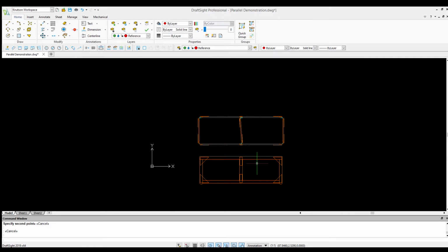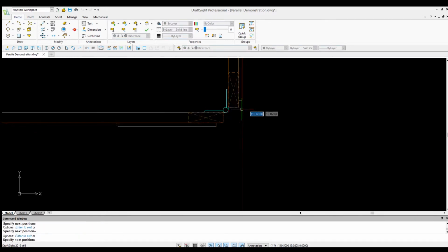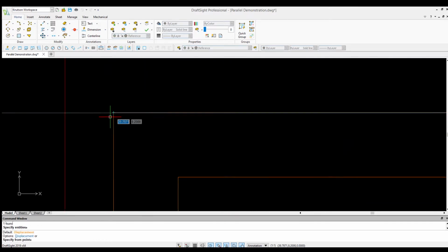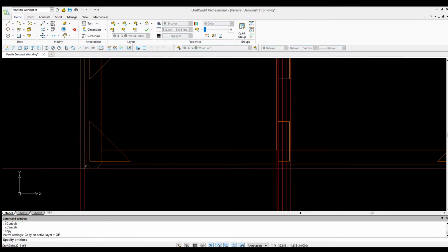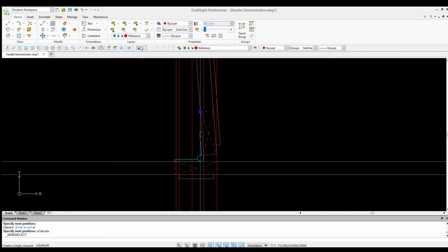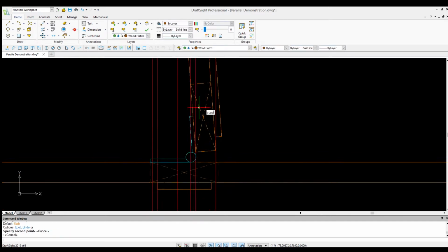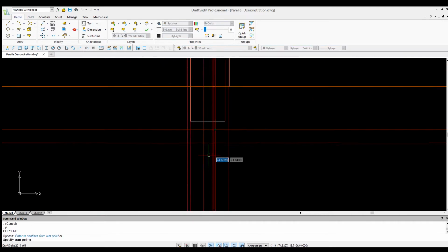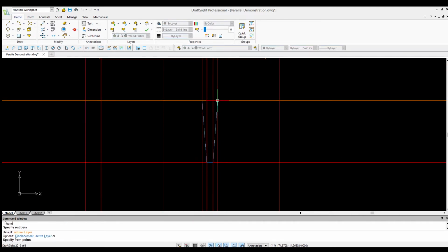In CAD, you can put objects on different layers to help keep things organized. I personally like to create layers based on materials, but there's really no wrong way to categorize layers as long as it works for both the draftsperson and the end user of the file. Here the orange lines and shapes represent lumber, and the light blue represents hardware, in this case the placement of hinges.